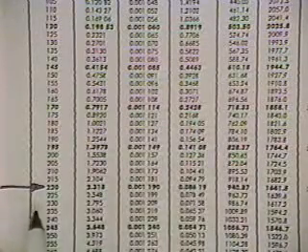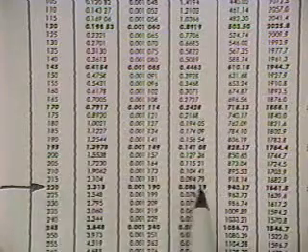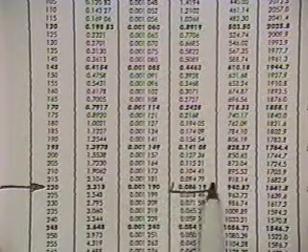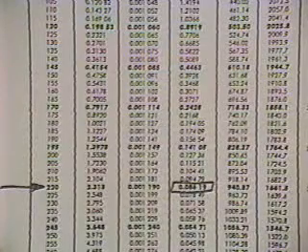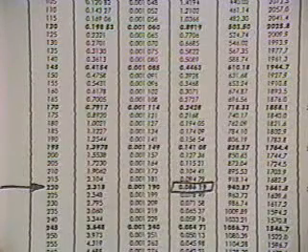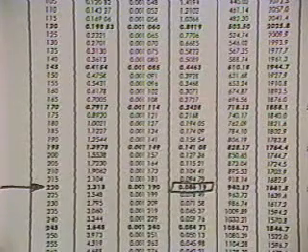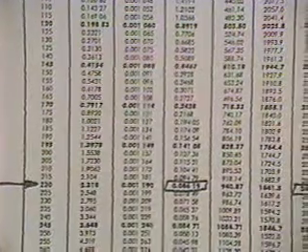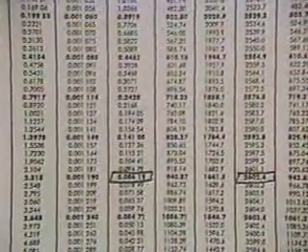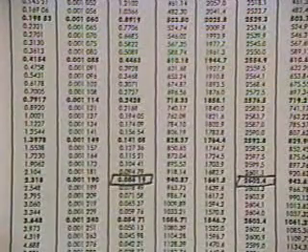And so from the tables on page 48 at 220 degrees C, you come over and you read a value of 0.08619 for the specific volume at saturated vapor conditions, and you can come over here at UG and read a value of 2602.4 for the saturated vapor condition.